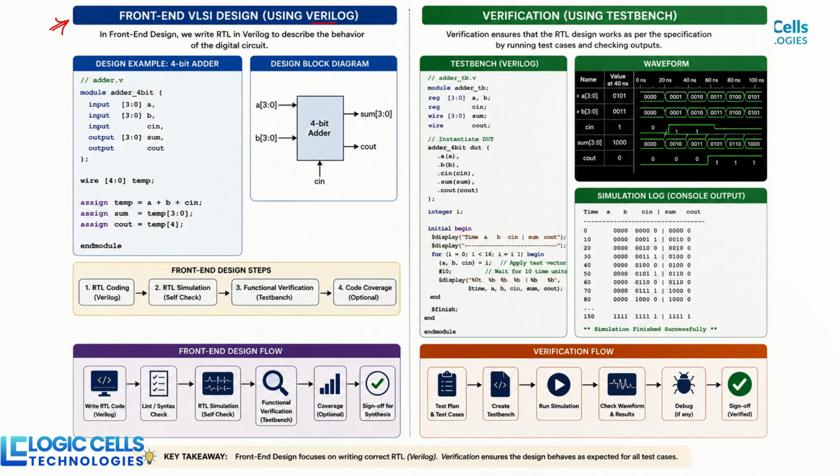I gave a very simple example yesterday. If it is a 2-to-1 mux design, we have only two inputs and one output. If we take A and B as inputs and output Y, A can be 0 or 1 and B can be 0 or 1. So there are only four combinations, and we need to provide all four input combinations and check the capability of this 2-to-1 mux.